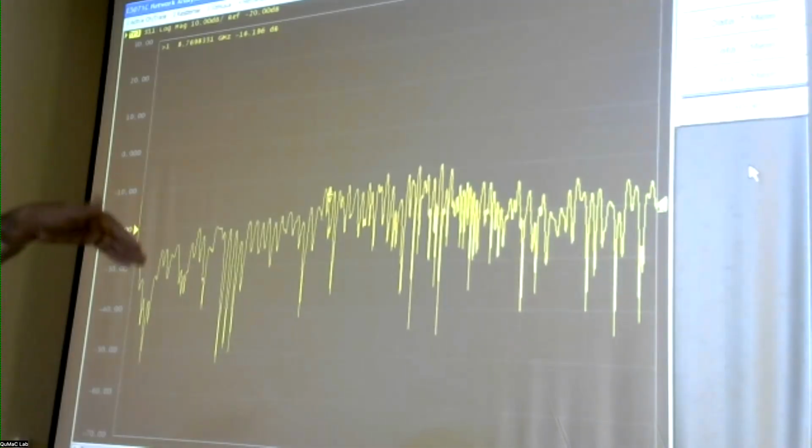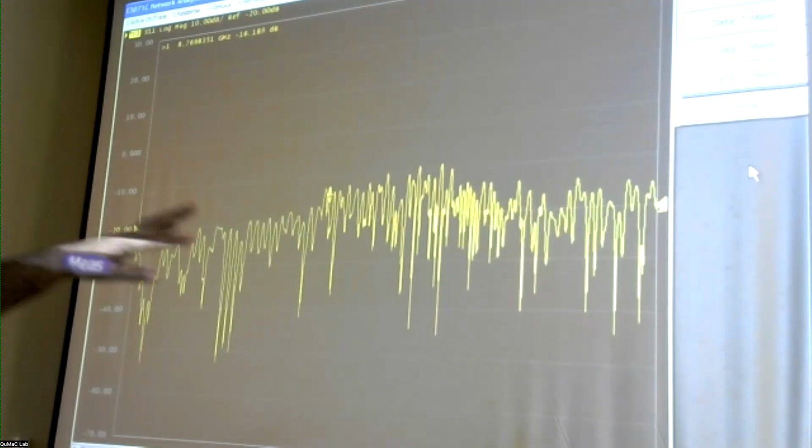You can do data divided by memory, data times memory, minus memory, plus memory. Usually the most commonly used one is the data divided by memory because you take some reference curve and you see how much it is increasing. So for example, if I was trying to measure an amplifier or an attenuator, I might connect a cable first and just measure the transmission, and then I'll add the attenuator and say how much does it change.